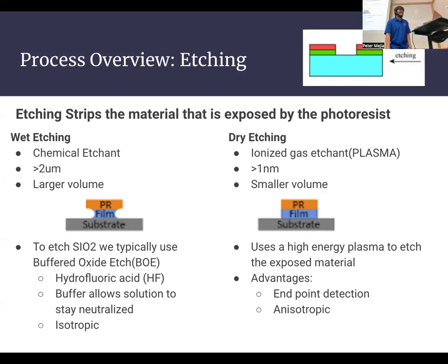It gives a bit of reaction, but sometimes in vents and stuff, you want it anisotropic. Oh, okay, cool. I didn't know that. Sorry, I could only hear bits and pieces of that in the end. Yeah, for MEMS, sometimes you want anisotropic etching. So in that case, you want dry etching for that one. But what are the downsides of dry etching?